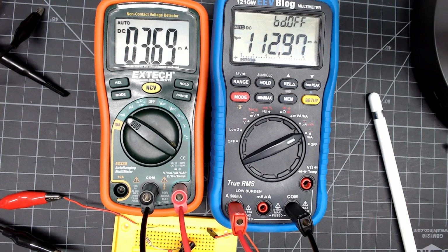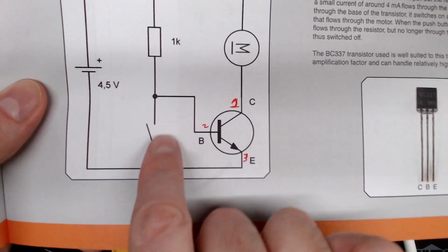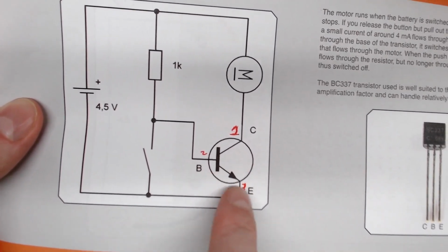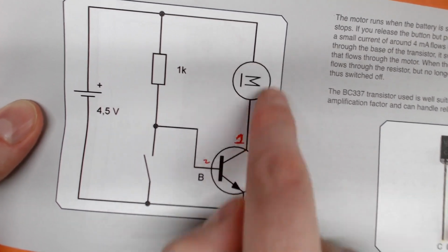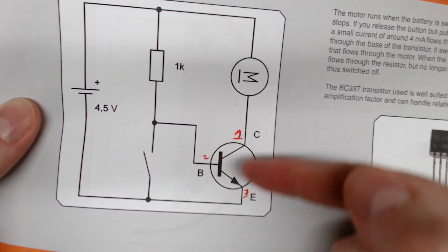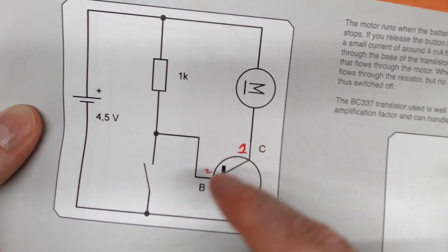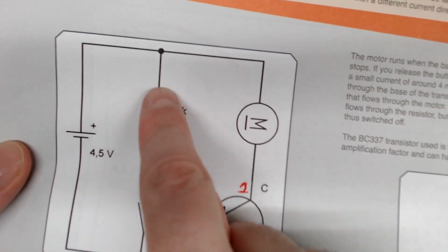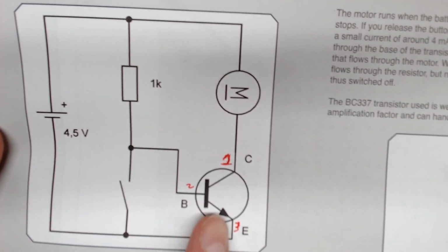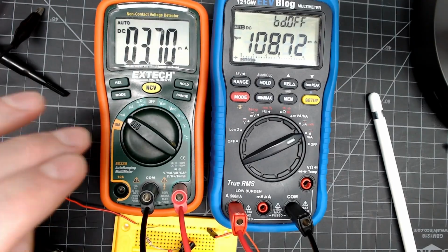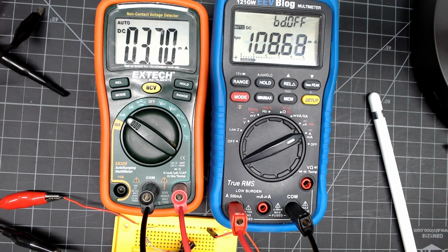If I press the button, what that's going to do is it's going to short this out such that there's nothing going through the base to emitter. So that's going to cause the motor to stop, because now nothing's going through here, so it can't go past that NPN junction. We're going to have similar current going through here. We're going to have a slight uptick, because we're not going to have this, probably 0.7-ish drop. So I expect to see a slight uptick when I do this through that resistor. So that 3.7 I expect to go slightly up. And it did. It went to 4.5. And of course, the current going through the motor is gone.